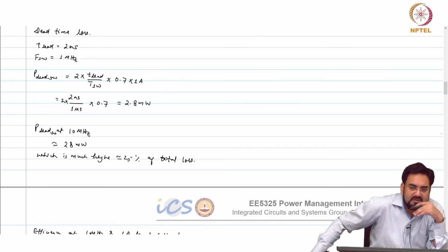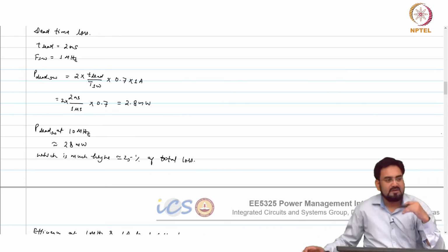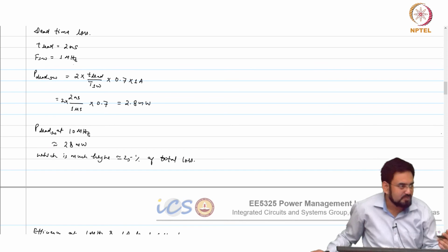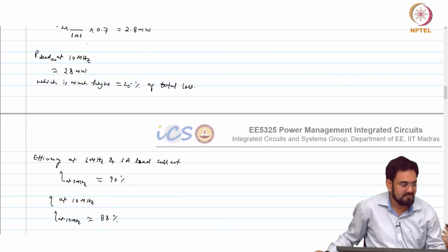So far, if you look at any product in the market, the targeted current is like 800 milliamp or less than that. So, 500 to 800 milliamp and 6 to 7 megahertz max frequency; more than 10 megahertz is very rare. But for this particular case, 0.18 micron and 1.8 volt input, 10 megahertz you can easily achieve.